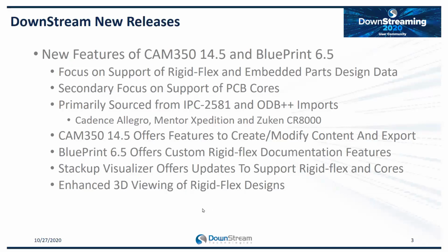Stackup Visualizer is a common tool between the two products, and it offers updates to support rigid flex, which typically has multiple stackups, and also PCB core definition. And to go along with this new data import and remodeling of the data, we also had to enhance our 3D viewing to support rigid flex designs. When you look at the layer strata of a database that we get from, say, Allegro, you've got core layers stuck in between dielectric layers. So we have to bring that all together and visualize it correctly in 3D.